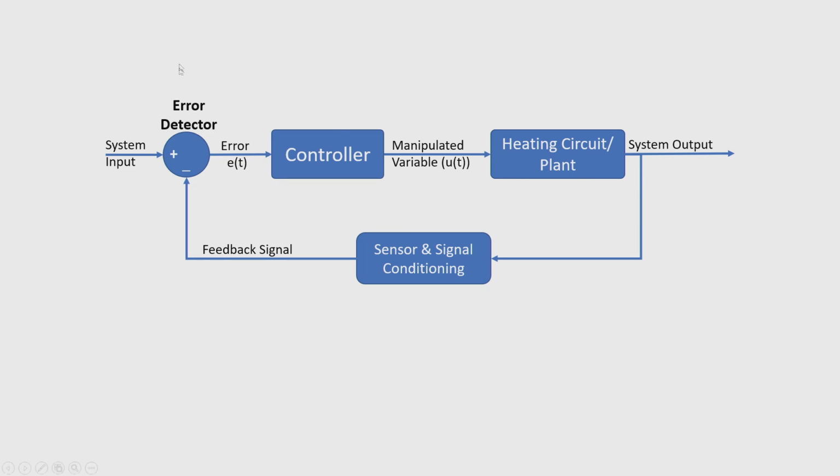In LabVIEW I will be developing the error detector, and the system input will also be controlled using LabVIEW user inputs, whereas the controller can also be realized inside the LabVIEW environment. The plant as well as the sensor will be externally connected to the data acquisition system, which acquires the data and displays it on the LabVIEW device.